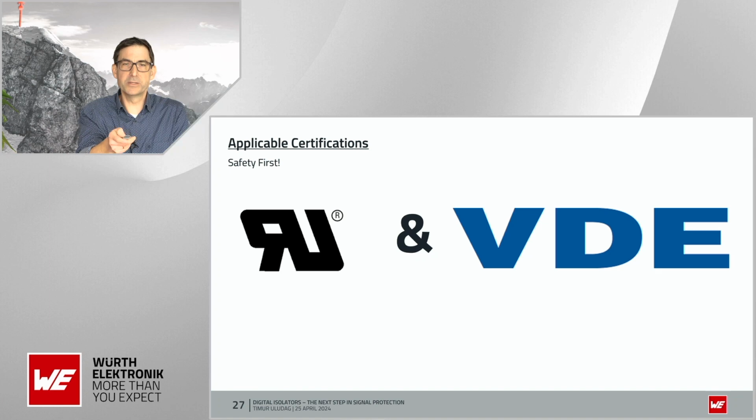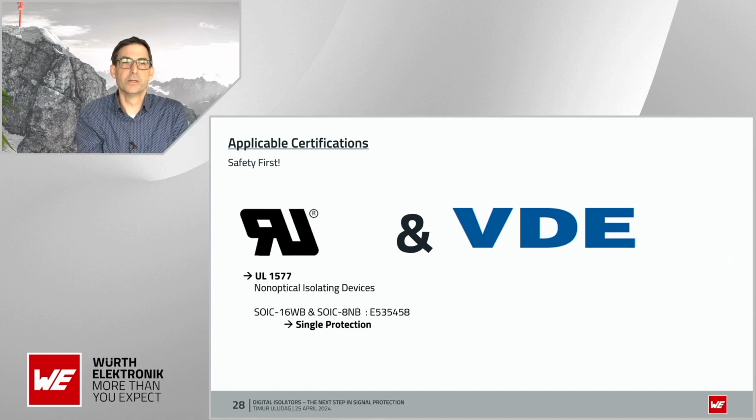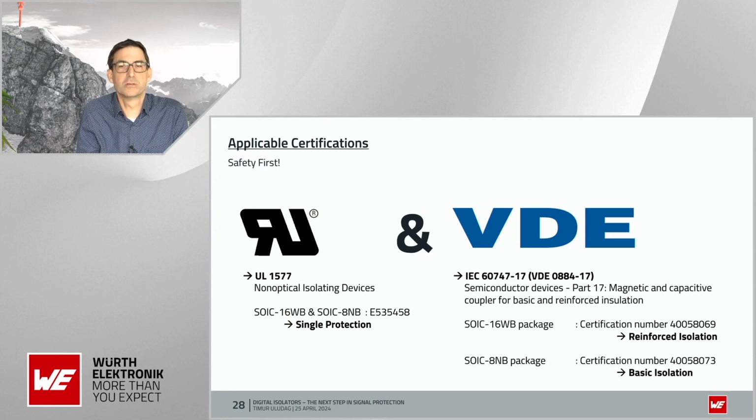Let us go a little bit deeper. For the UL, we go for UL 1577. We have got, for the whole portfolio, a single protection certification. And for the VDE, we took, from my perspective, the standard that makes the highest demands in durability and safety, the IEC 60747-17. This is a quite new standard that came up in 2020, 2021.